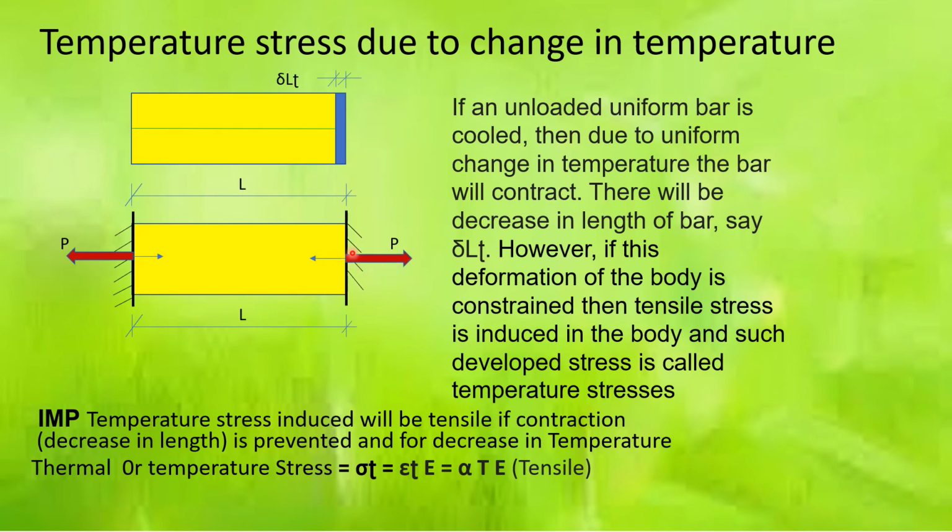If this tensile force is developed, then only it will prevent the contraction of the bar, and the bar length will be L. So however, if this deformation of the body is constrained, then tensile stresses are induced in the body. So this tensile stress will act on this rod, and such a stress developed is called temperature stress.